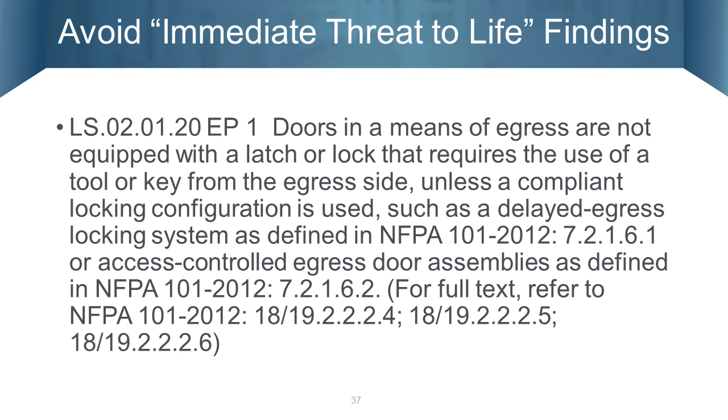Okay, means of egress not equipped with a latch or lock. What we're finding here is magnet locked doors in a means of egress, whether it's to lock people out of a department, for instance to lock them out of OR, or to lock other areas. If it's a means of egress with an exit sign above the door, and there's a possibility that anyone can get to where that is, even though employees can badge swipe and get through that magnet locked door, if John Q. Public cannot, it'll be a finding.